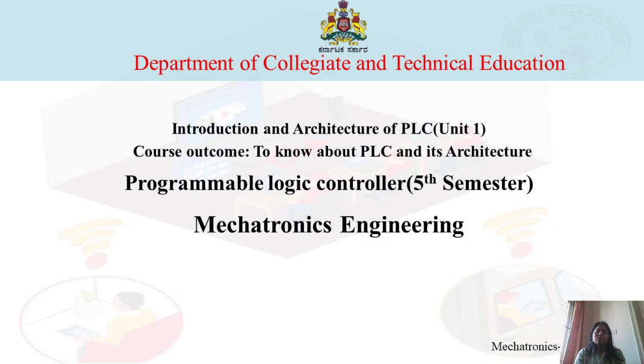Understood? And after that, we have studied the difference between relay logic control and PLC logic control. Why today all industries have shifted from relay logic to PLC logic control. In the relay logic control, as I already told you, it requires more wiring for the components, and for complex systems, reprogramming is very difficult and it occupies a large space. In case of PLC, even for larger systems, you can program it at less cost. Understood? The human effort is also less.